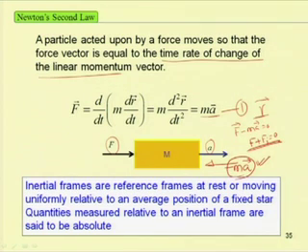The inertia force acts in a direction opposite to that of the acceleration, and by adding the external force with the inertia force, we can convert this dynamic system to a static system. The disadvantage is that the parameters we are using, the force and the acceleration, are all vector terms, so they depend on both magnitude and direction.